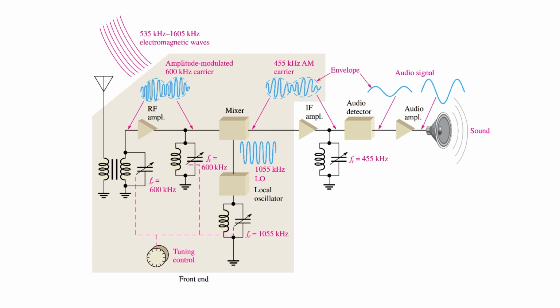A slightly more complicated circuit employed by your radio receivers is this superheterodyne AM radio broadcast receiver. Let's say that you want to listen to a radio station at a frequency of 600 kHz. The radio station sends out that specific frequency uniquely assigned to it. The transmitted signal, that is, the music or whatever audio, is carried by this 600 kHz frequency as an envelope. In the figure, it is represented by the border lines enclosing the main signal.